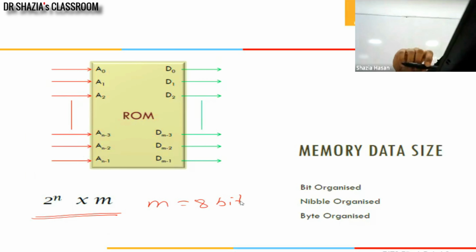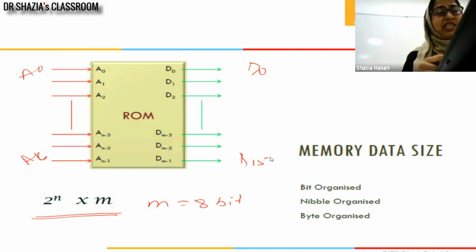Here it is shown as ROM. ROM is read-only memory; we can only read the data present in the memory, we cannot write. So those control signals are not shown here, and the address lines we will have as it is. For the 8086 processor, my address lines will go from A0 to A19. The data bus will go from D0 to D15. You can see the data bus is coming out from the memory, only read operation. It can only transfer data from memory to the processor. The data bus is not bidirectional here.